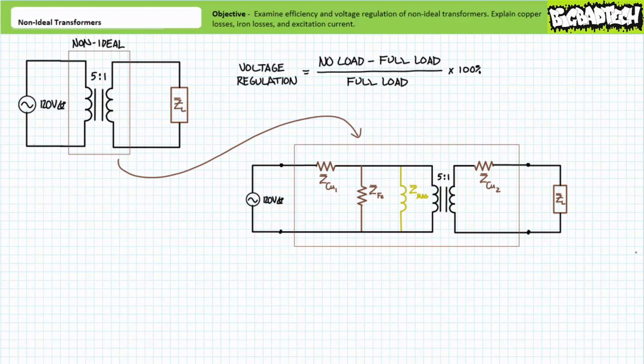to the transformer. In a sense, voltage regulation is a current-dependent phenomenon that occurs in two stages. Recall we earlier observed current drawn by the reflected impedance and the parallel leakage paths must travel through the resistor, accounting for the internal resistance of the primary windings, and as such, a small voltage drop occurs.